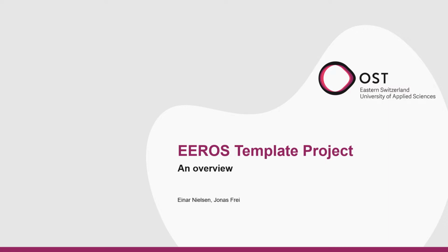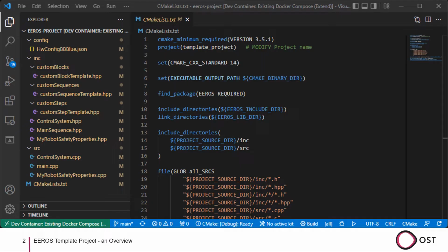The EEROS Template Project is a great starting point for developing your own custom EEROS applications. It contains the three basic systems of EEROS: a safety system, a control system, and a sequencer, along with a configuration file that can be used to access the hardware of the BeagleBone Blue and the main function that launches the entire application. But let's jump right into the development environment and take a look at the various files.